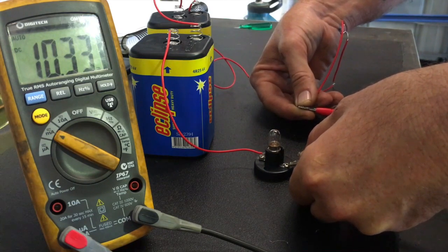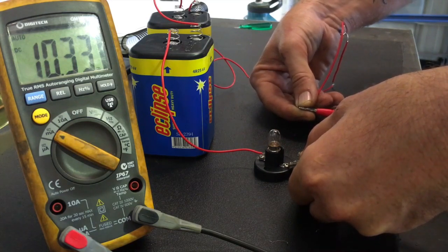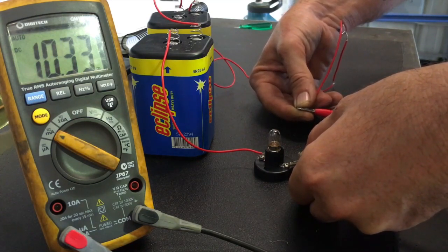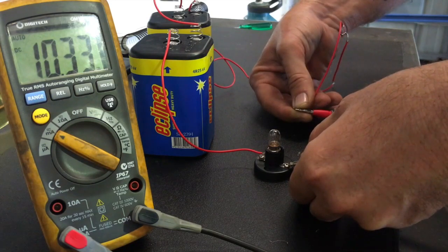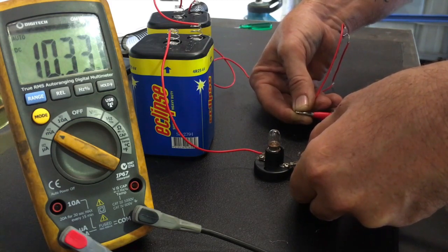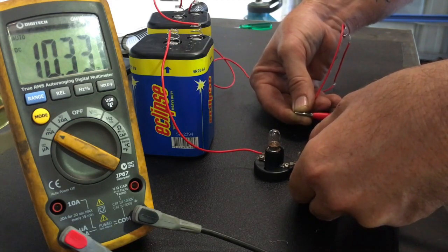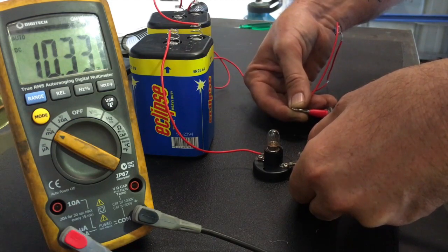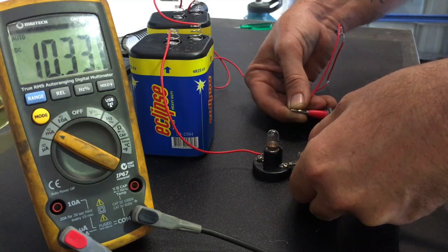So once again that agrees pretty closely, other than the rounding error, with the theoretical calculations we made. Now if you know how much current a circuit's supposed to be drawing, and you think, oh, hang on, this globe actually draws an amp to run, it's only getting 10 milliamps, that is a way you can detect that there's way too much resistance in the circuit because nowhere near enough current's flowing.